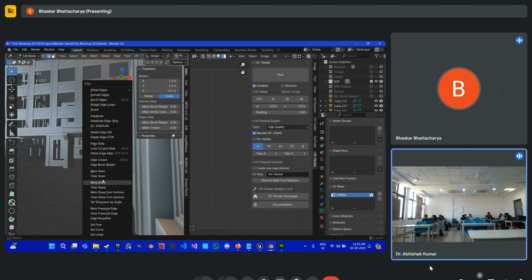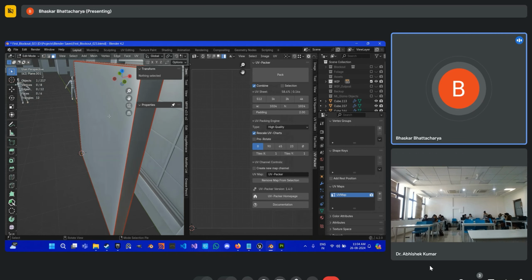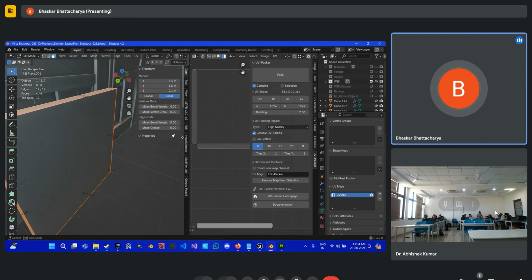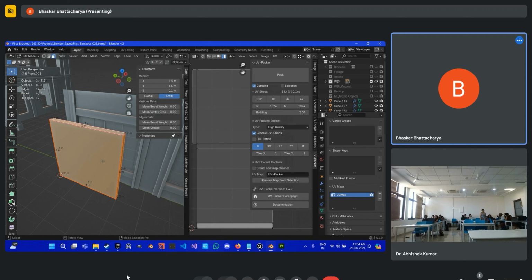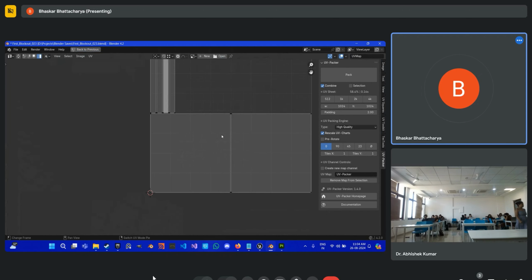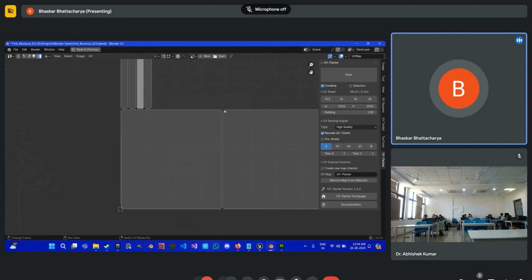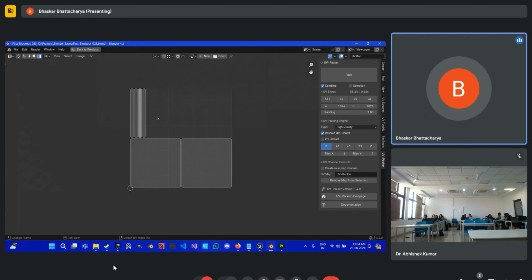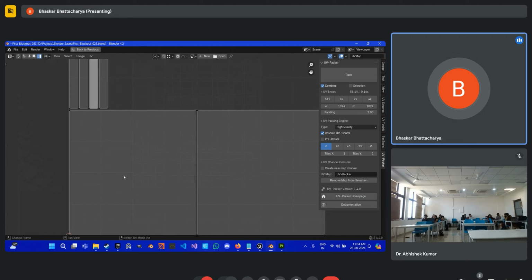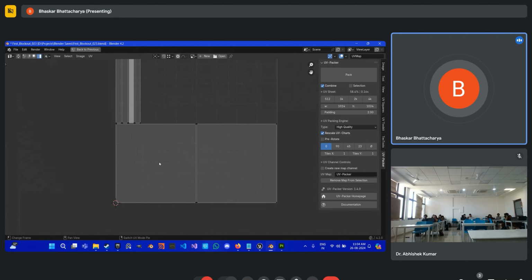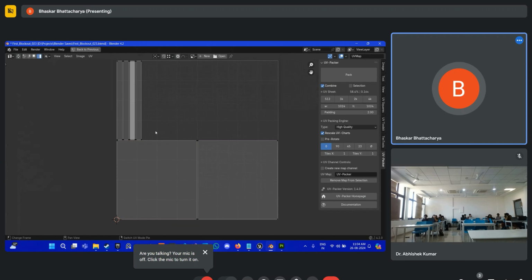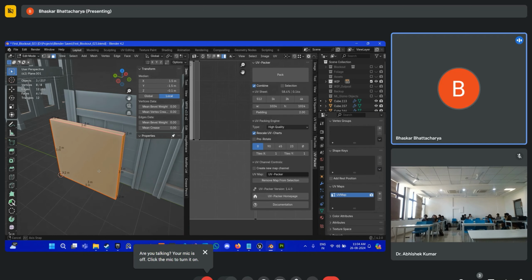And this is because this is going to be a wall. We may not see these faces anywhere. So I'm going to unwrap this, and this occupies more UV space. As you can see, these faces have much better resolution. This is called the 0 to 1 space. I hope you're aware of that. So in 0 to 1 space, we want to give our UV maps as much space as possible, as big as possible without breaking anything.